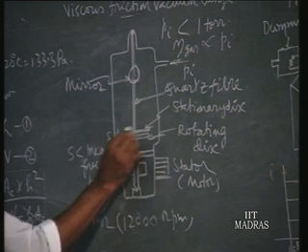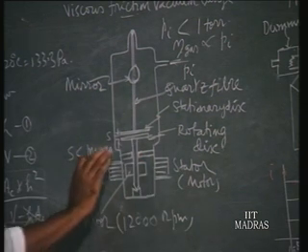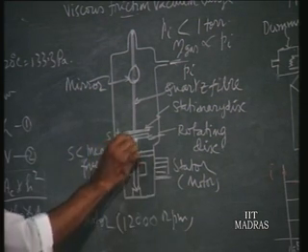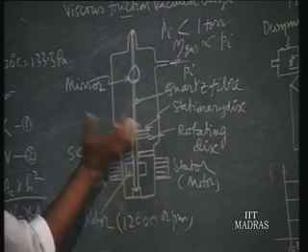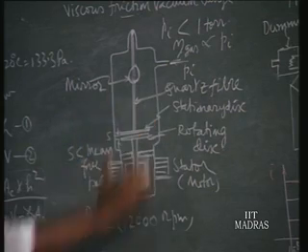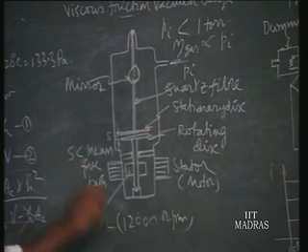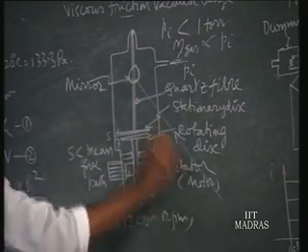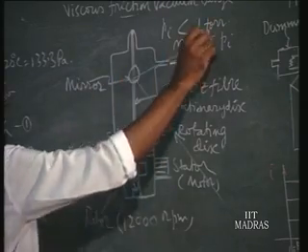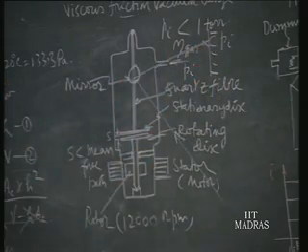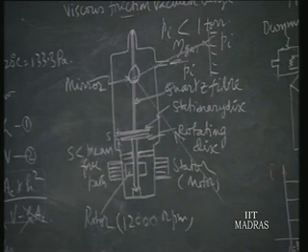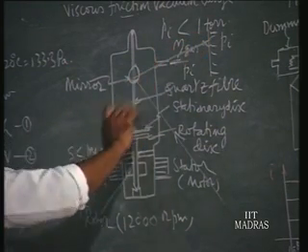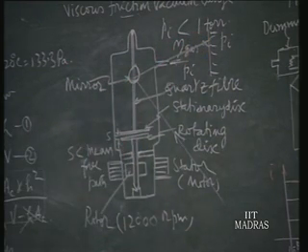Due to the presence of molecules, there is some viscosity. Due to viscosity, the torque from the rotating disc is transmitted to the stationary disc. So due to the torque, it will tend to twist, that is, we have a quartz fiber with its elasticity. A light ray from the source is reflected to an optical scale, which is written in terms of vacuum pressure. So for different pressures we can get the reading, and for each gas we have to calibrate this instrument. After calibration we can use it.